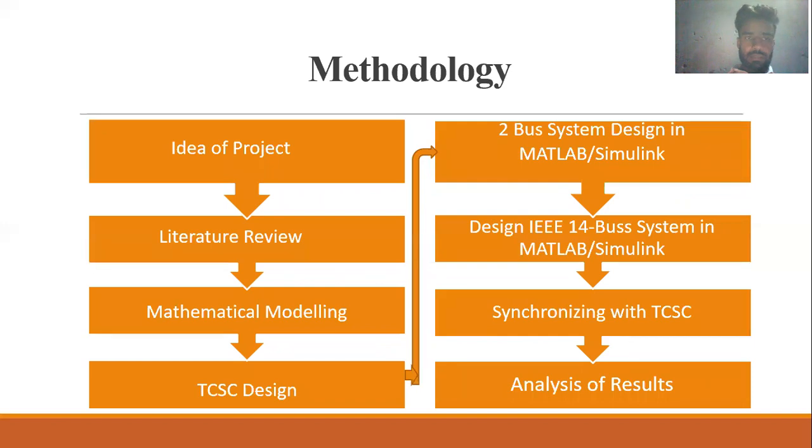Then we did the TCSC design in MATLAB simulation, then moved to the two bus system in MATLAB Simulink. Then we extended it to the 14 bus system, and then we synchronized it with the TCSC 14 bus system, and then we did its analysis and collected some results. On the basis of this, we are interpreting.